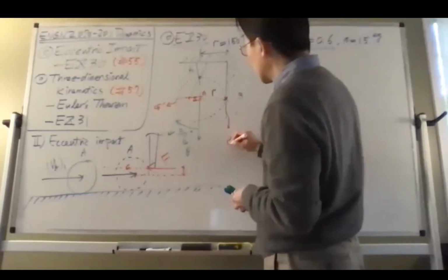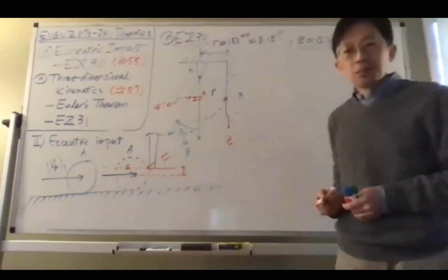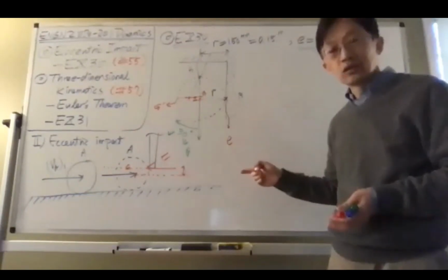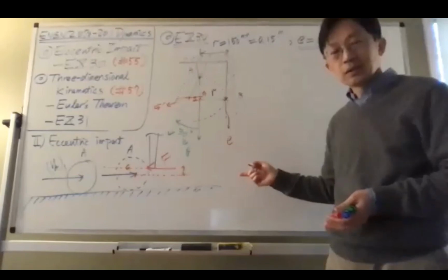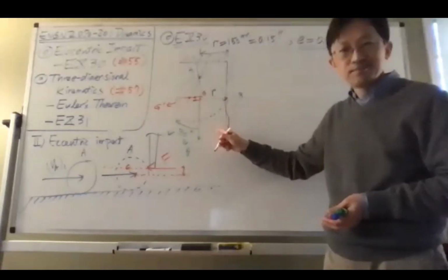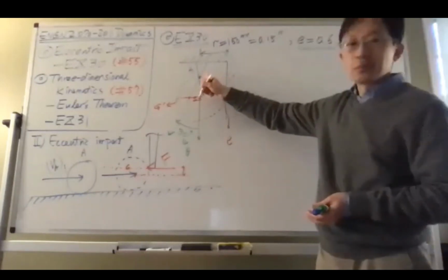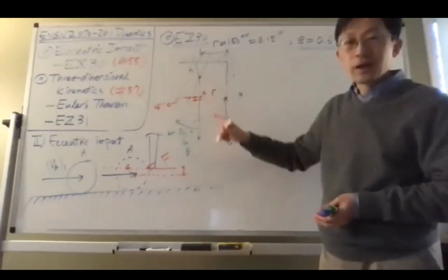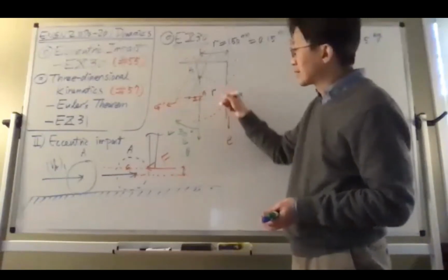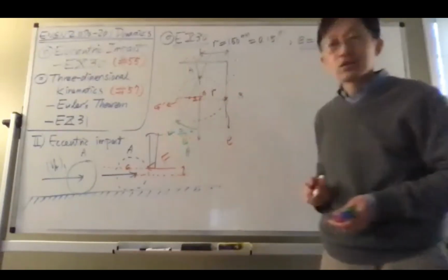This is where the e is doing its own business. Because e is not 1, that means some of the energy is going to be consumed. But realistically speaking, there's air friction, right? And there's also friction at the support, which is why, realistically speaking, you will never expect that it will go back to 30 degrees.